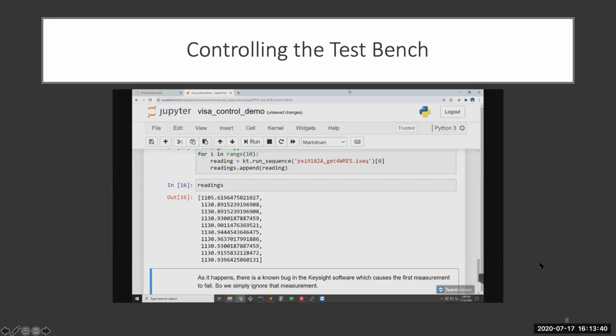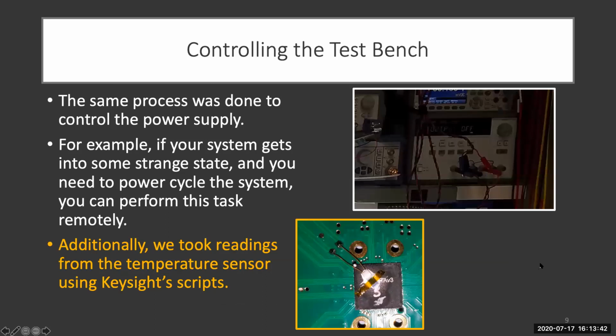Okay. So to summarize, in the demo, you saw me check the status of the power supply, which sits on the test bench. This was done with GPIB. And additionally, I demonstrated taking readings from the temperature sensor that's glued onto the exterior of the chip, and that's a picture of that here. So this is the temperature sensor that we just measured.